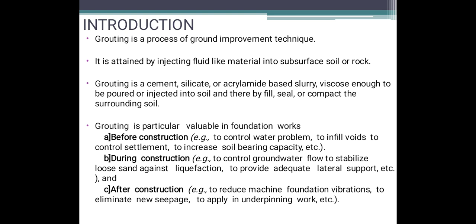support. After construction also we have some applications of the grouting technique: to reduce machine foundation vibration, to eliminate new seepage if any, and to apply in underpinning work. Underpinning work is nothing but foundation work.